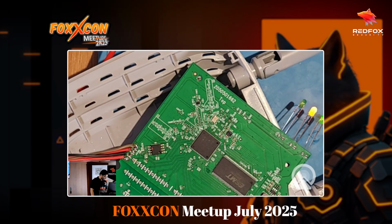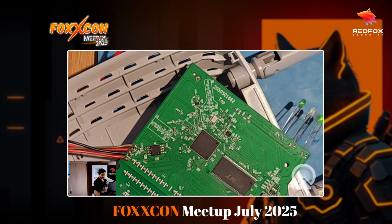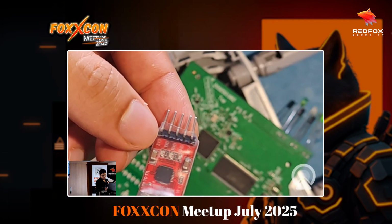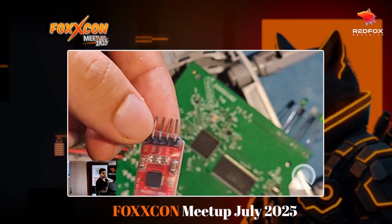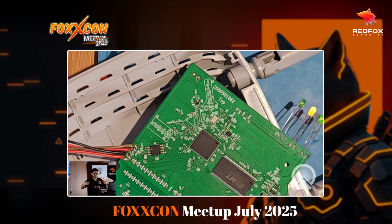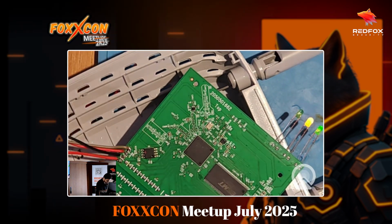Now since I've already soldered these cables to it, I'll just be connecting that to the same thing on the USB TTL adapter that I mentioned earlier. As I told you, receive should go to transmit and transmit should go to receive. It's a cross connection since they should be able to communicate with each other. Anyways, I'll just connect that up quickly.